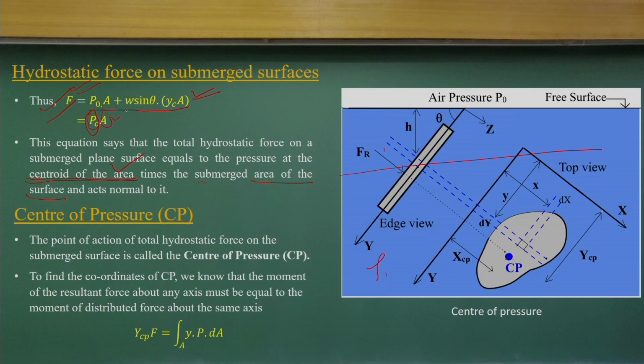But if you have a simple one-fluid system, then the density is a constant. You find the CG, and at that point you find what the pressure is. You can just equate it to atmospheric pressure plus the height, that is, the depth of the point below the free surface. If you know the pressure at this point and multiply by this area, what will you get? The force component.